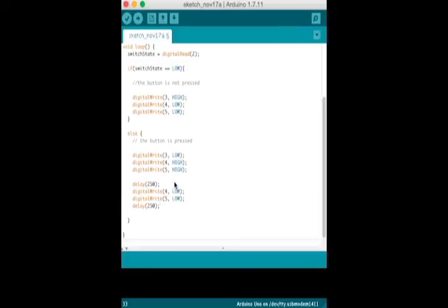And that looks like that's the code. Once your Arduino is programmed, you should see the green light turn on. When you press the switch, the red lights will start flashing and the green light will turn off. Try changing the time of the two delay functions. Notice what happens. Okay, so I need to program this code or upload it to the Arduino, so I shall stop this recording now.